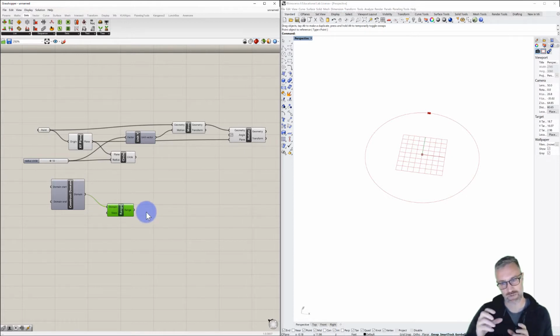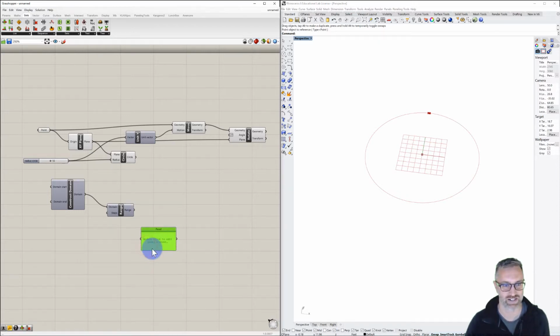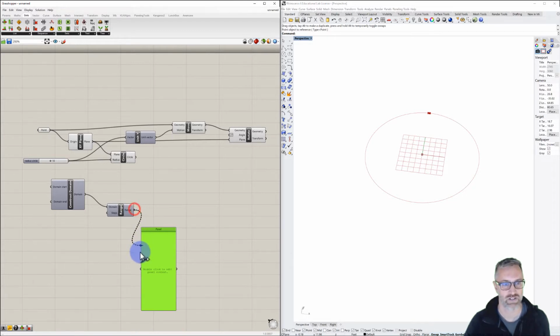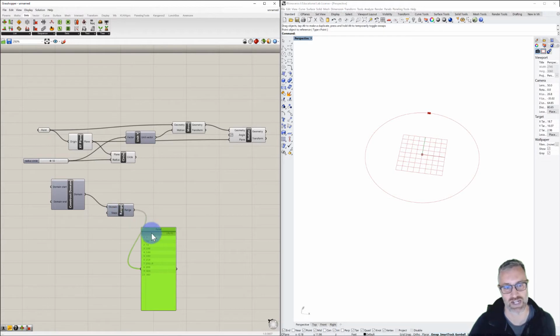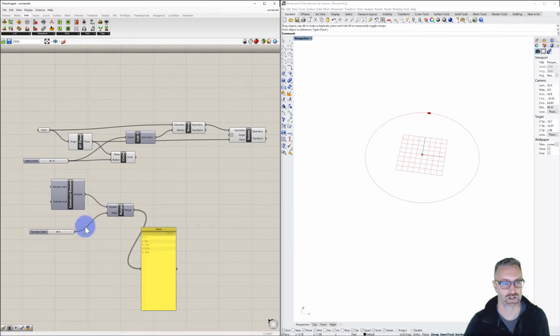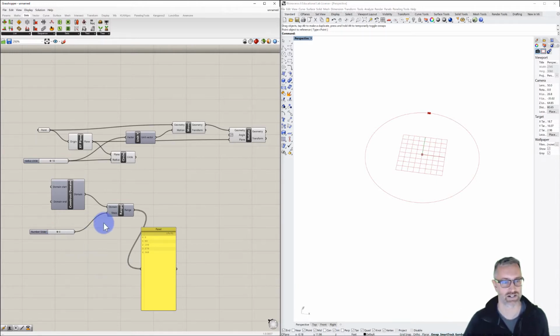And as we manipulate the data as it relates to this range, I want to create a panel, which you'll see in a few minutes will be a whole set of panels, just so that we can track the evolution of our data as we build it to send it to our rotation. And let's set our number of steps as well. Right now the default steps is 10, and we can see it's going from 0 to 360. That's what we want. Let's set our steps with a slider. Let's say 1 is less than 4 is less than 10. I actually want to have a small number of steps here. 3 or 4 is good, because you'll see in a second, we're going to duplicate this data. So we can see from our panel, we get 0, 90, 180, 270, and 360.